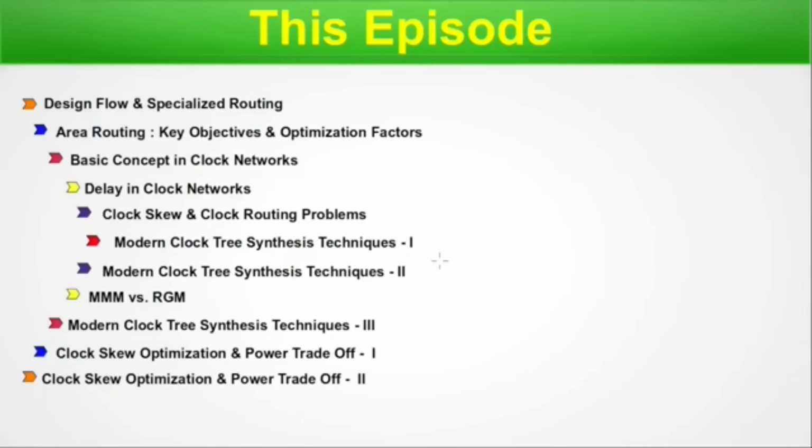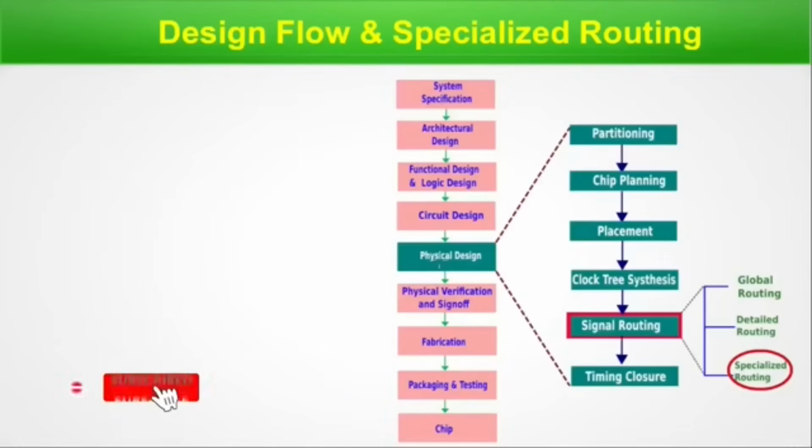We are done with this slide. Now let's move to the next slide. Design flow and specialized routing. This diagram we have been using for the last few episodes, and today also we will take reference of this one. Once the flow enters physical design, there are multiple steps like partitioning, chip planning, placement, clock tree synthesis, signal routing, and finally timing closure. So in signal routing, we have already covered global routing and detailed routing, and today it's